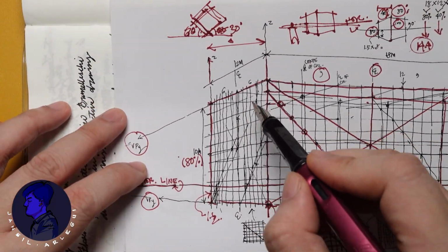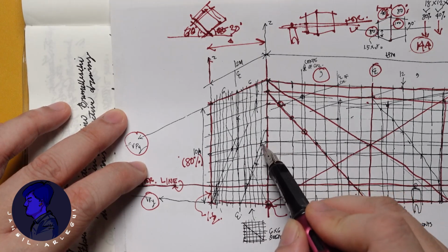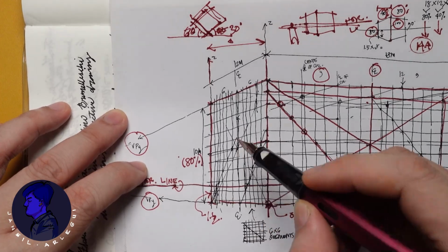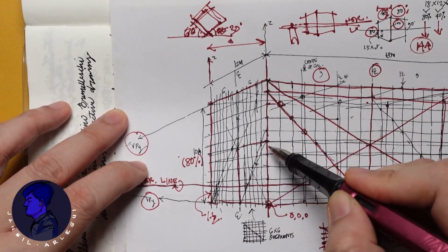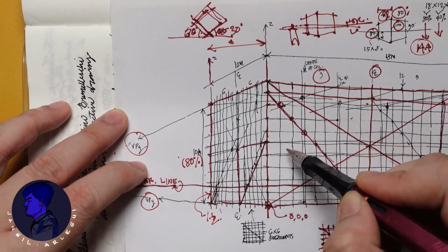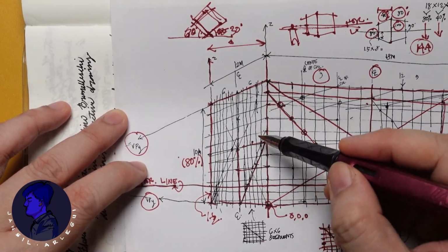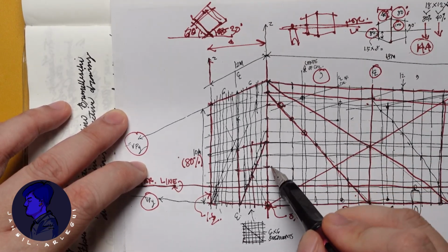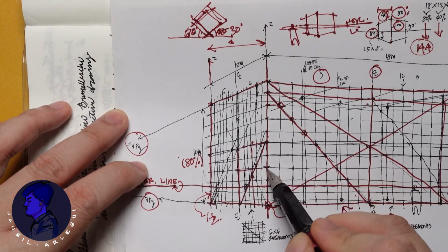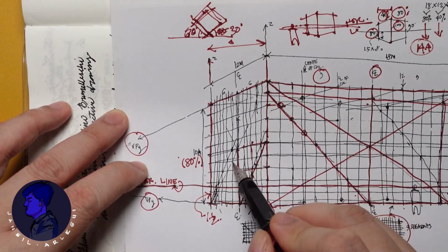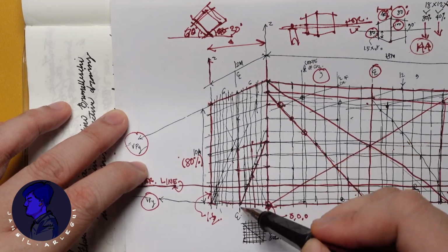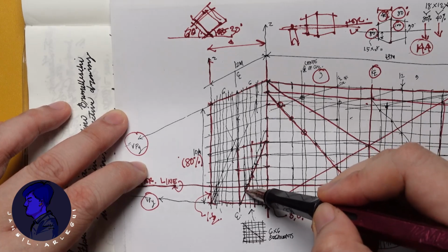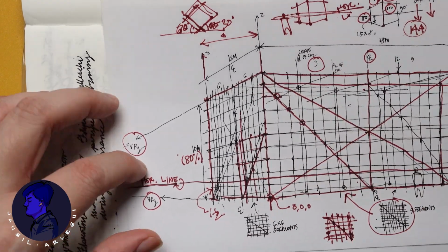Now here, we only have 6, so you can count 1, 2, 3 until 6. And you can imagine this as your square, draw a diagonal line, and subdivide these into 6 equal parts. So I can X this, I know where this is, so I need to segment this into 3 equal parts later on. Then draw the horizon line, draw the diagonal line here, and where they intersect, that's where you subdivide your vertical lines.